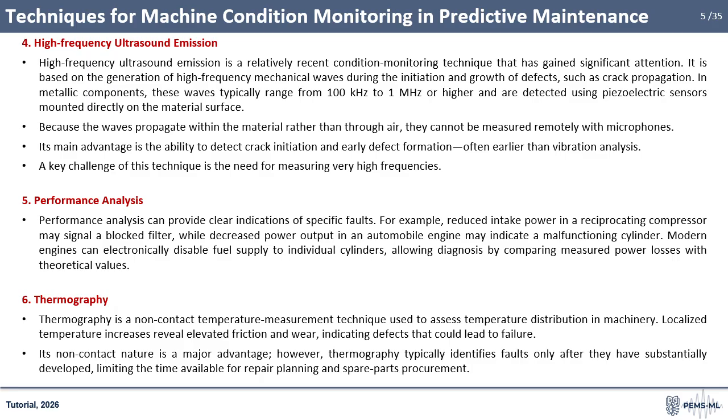Because the waves propagate through the material rather than through air, they cannot be measured remotely with microphones. The main advantage of this technique is its ability to detect crack initiation and early-stage defects, often earlier than vibration analysis. However, a key challenge is the requirement to measure very high frequencies.